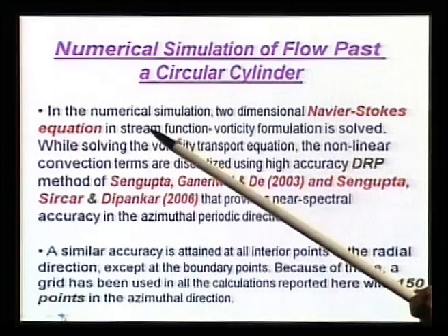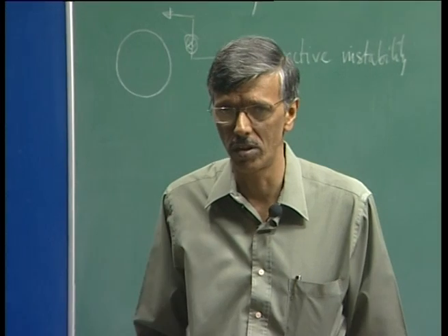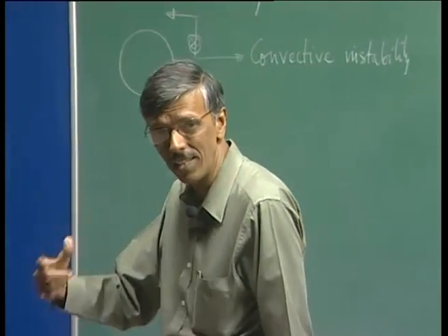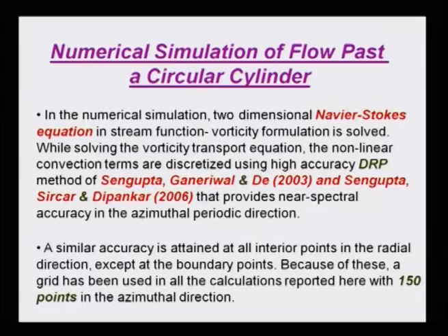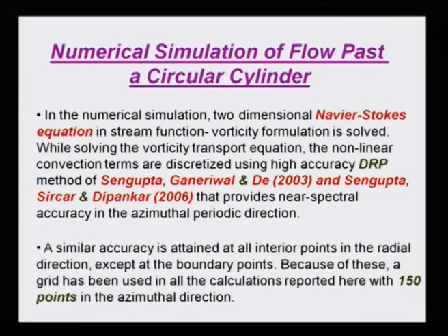The moment you use stream function as a dependent variable, you obviate the need for satisfying mass conservation. It is automatically, analytically satisfied everywhere. And since we are looking at vorticity dynamics, studying vorticity itself as the other parameter is a very attractive one, and we do see the point.